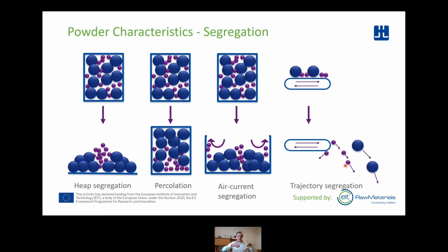It's only if you make very big size parts with quite a high fill depth, so you have a big tool cavity to fill in the compaction process, then this is something that will have to be considered. And again, organic bonded mix, where you bond the finer particles to the base powder particles, is an efficient way of counteracting this type of segregation.